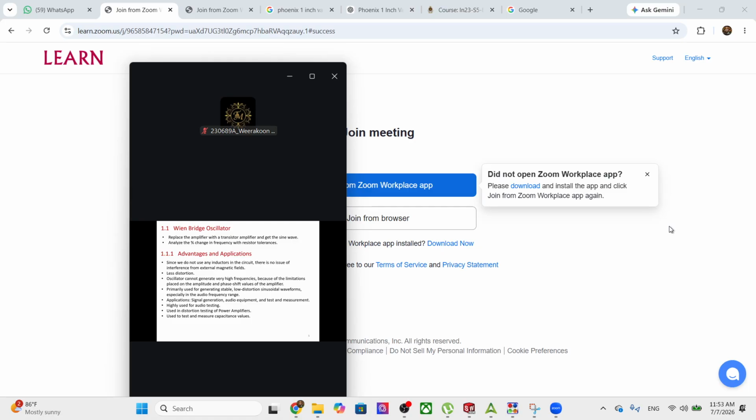Normally, when you design an amplifier, what will be the input to that amplifier when you do the testing? It is a sine wave, right? If you do not have a signal generator, how do you do that testing for simple circuits? You can generate it with a Wien-Bridge oscillator with one op-amp, very low cost. You can design it. That is why in your first lab, you are going to design a Wien-Bridge oscillator, which gives you a range of frequencies.